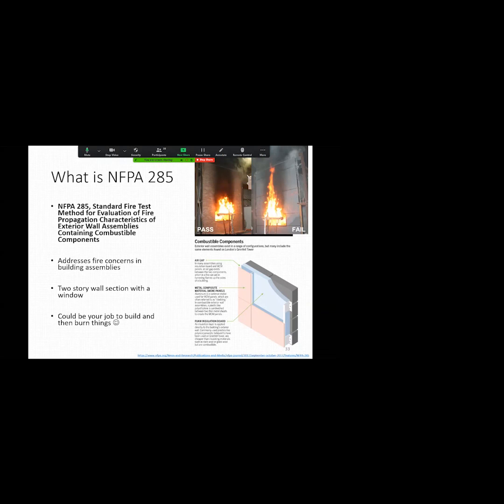When styrofoam melts, if you don't put breaks, and if you look at this picture down here, it shows some of these breaks that they have in the insulation. When this stuff melts and it's on the exterior of your building, or even if it catches on fire and there's no breaks in this stuff, it acts as a channel or conduit for fire, or it can act like a chimney and melt and draft and pull hot air up, and the fire will go along with it.